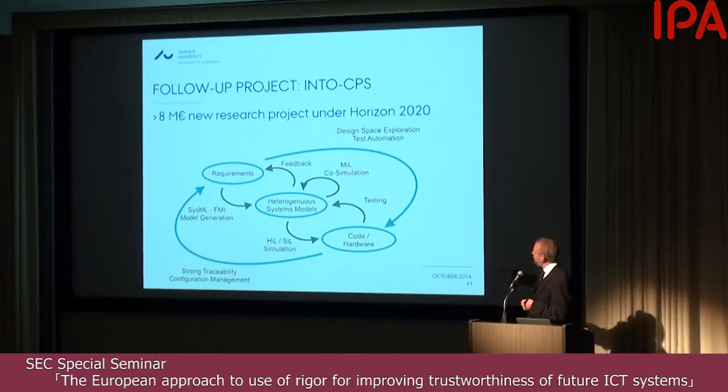This project is going all the way from requirements using SysML down via heterogeneous system models that can be simulated at the modeling level using an interface called functional mock-up interface, and then also having hardware in the loop and software in the loop simulation capabilities together with code which is being generated or actual pieces of equipment, actual hardware.